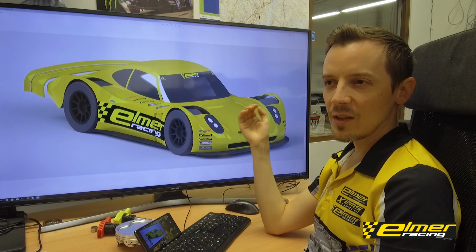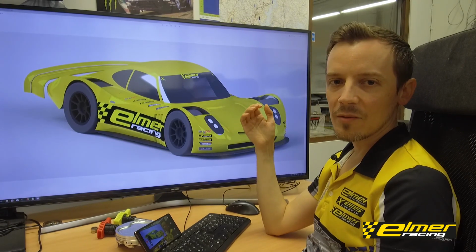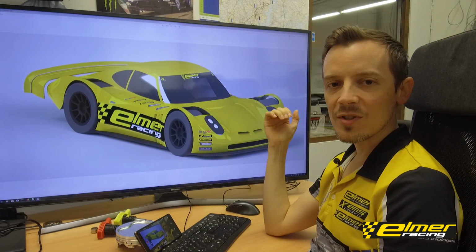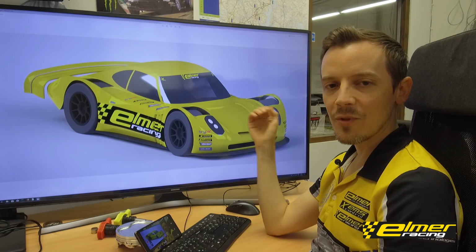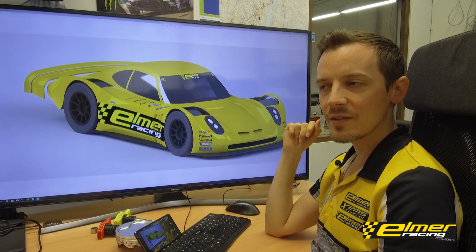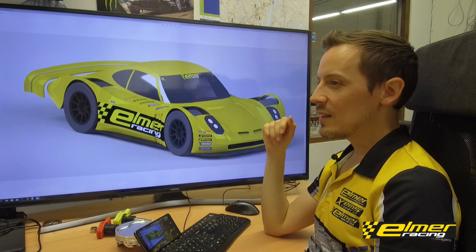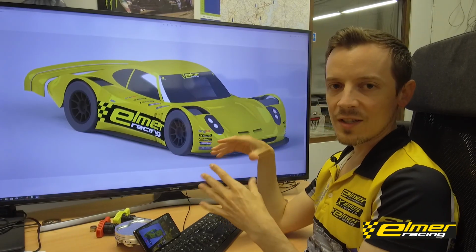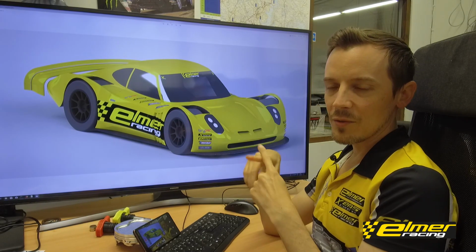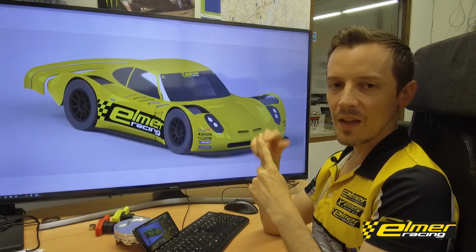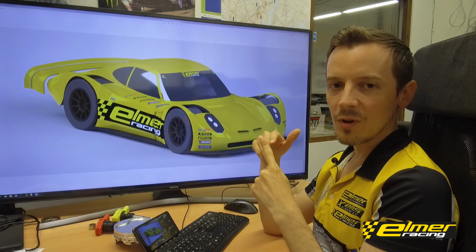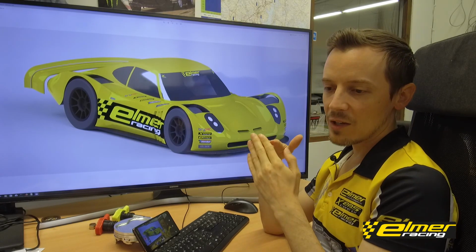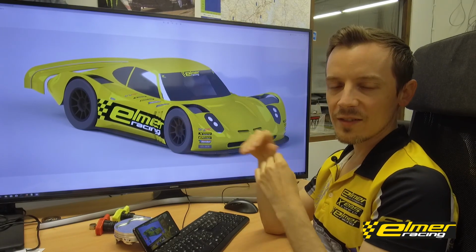Even in the wind tunnel testing they did in the Group C days, running thousands of hours of wind tunnel testing for car development, you have issues, because you would run scale models. With a scale model you have to have the Reynolds number the same, and then at the speeds they were going you also need to have the Mach number correct.